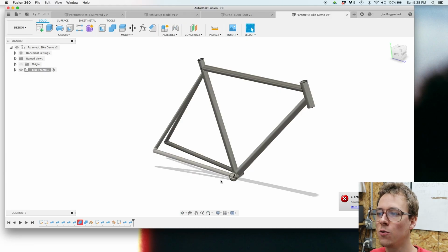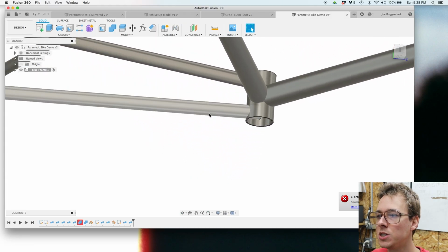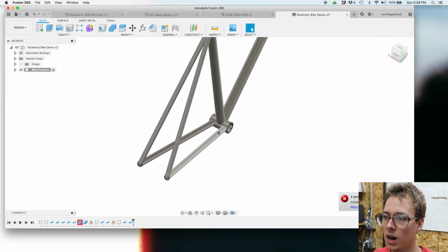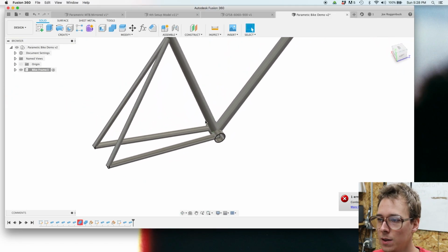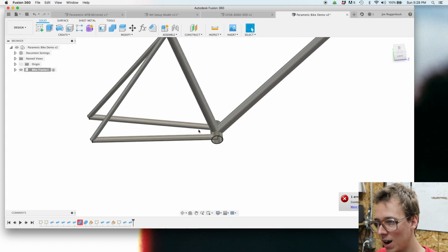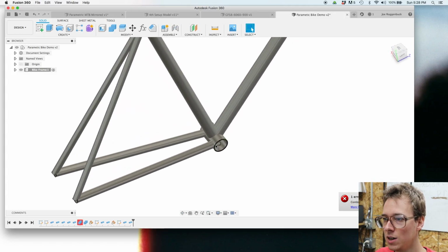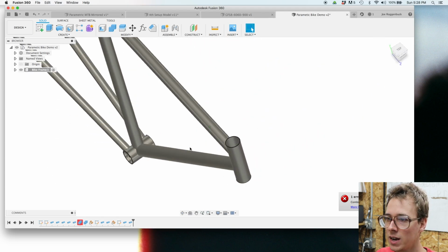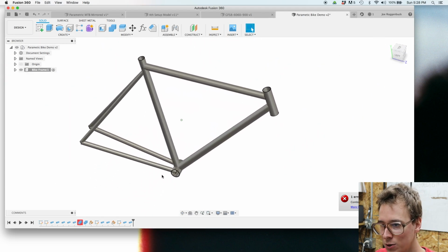Think about the potential in the rear end of the bike here, between the chain rings and the tire. That's a super duper pinch point. Just about every builder who's built anything with short chain stays or fat tires has wanted to pull their hair out trying to deal with that. Well, imagine, chain rings sit at a particular distance off of the frame center line, and they're of a particular diameter. You can model those pretty easily.